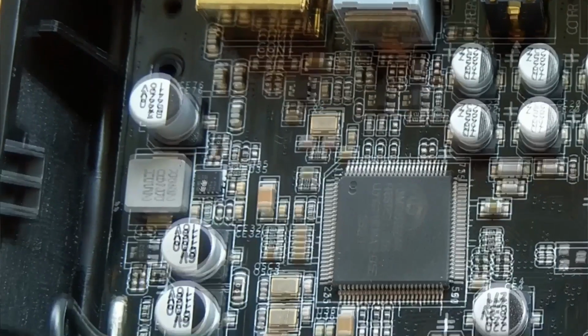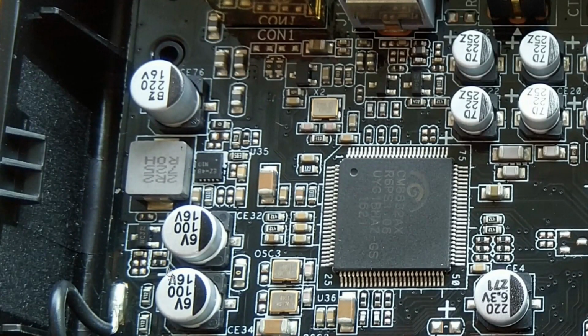What we have over here is clearly the power supply section. We have some kind of small switch mode controller here. It looks like one of the Texas Instruments parts. This most likely generates a constant 5 volt output. These little things switch at a very high frequency, something like 1 megahertz, and we can see the inductor is quite a small value, just 2.2 microhenry, and we have a few capacitors here.